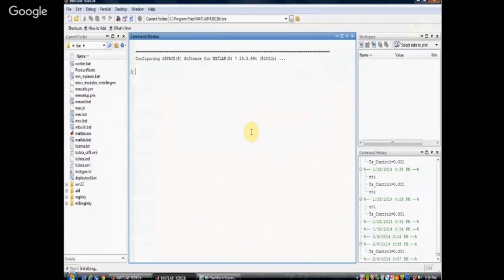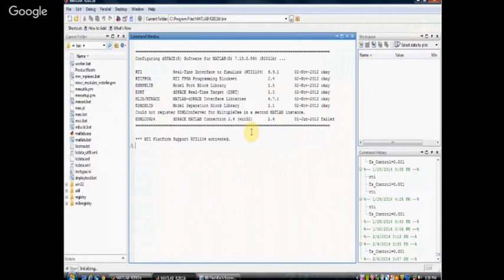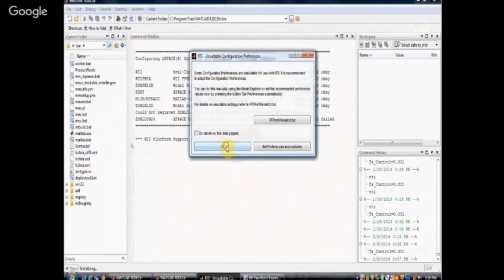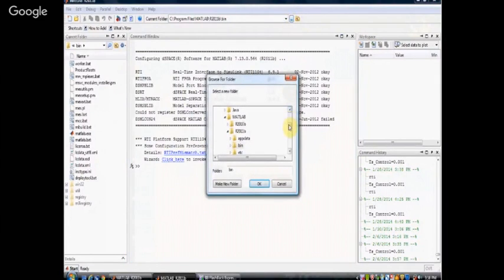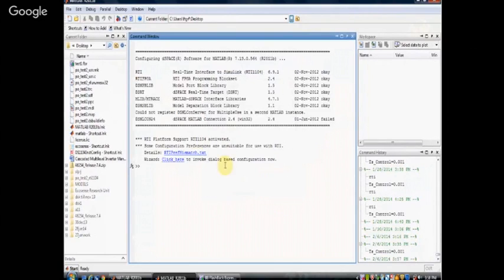For DSpace, a key is also required. You have a pen drive like thing, so you have to put that in. So here you just click OK, and now a command prompt will come. Whenever you want to connect DSpace, you require a key. A pen drive is required there. So now I'm just going and choosing my program. My program is in the P&O, perturb and observe. In desktop it is available. So I'm just going and choosing my program.